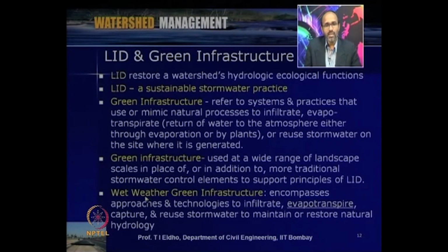Then another term related to green infrastructure is wet weather green infrastructure. This encompasses the approaches and technologies to infiltrate, evapotranspire, capture and reuse the stormwater to maintain or restore the natural hydrology. So, in all these LID or green infrastructure approaches, the major emphasis is on keeping the natural ecology with minimal development, and giving the possibility of more recharge to the ground or to the aquifer systems, and then reducing the pollution.